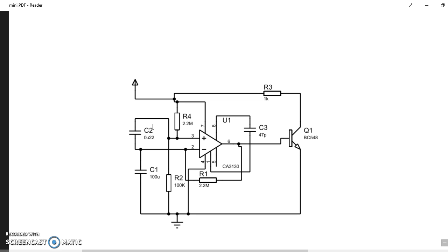Capacitor C1 along with high value R1 keeps the non-inverting input stable for easy swing of the output to high state. Resistor R2 provides the discharge path of C1. Feedback resistor R3. This R3 makes the inverting input high when the output becomes high. Capacitor C3. Function of capacitor C3 is like a strobe. Capacitor C3 is connected to pin 8, that is the strobe, and null input, that is pin 1 of the IC, for phase compensation and gain control to optimize the frequency response.